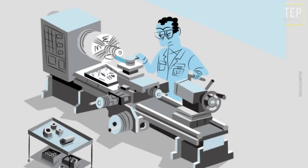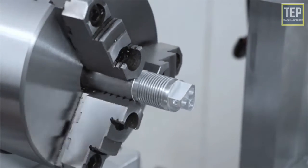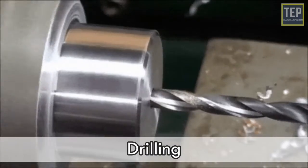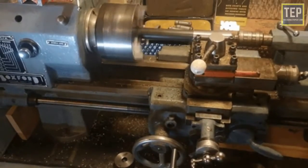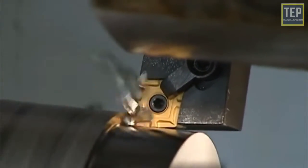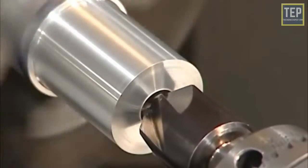A lathe is a machine that rotates the workpiece about an axis of rotation to perform various operations such as turning, undercutting, knurling, drilling, facing, and boring. The cutting edges of tools are applied to the workpiece to create an object with symmetry about that axis. A single-point tool is used for general work purposes, but for special operations, multi-point tools may be used.